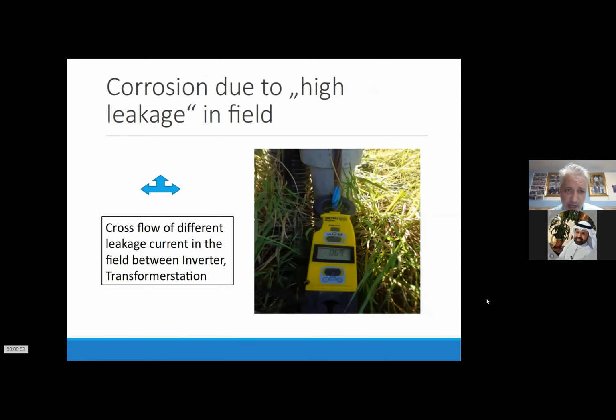And the high leakage in the field, like I said, this was in a pumping station. So you have 690 or almost 0.7 amps, so 690 milliamps running constantly on this earthing. And once you walk through the field, you can see the blue or greening of the copper conductor.